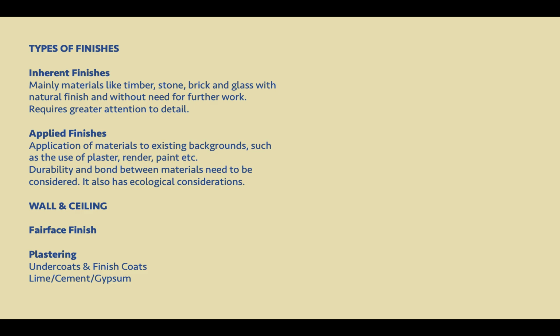Moving on from basic plaster, you will also look at plastering on timber, which will include the use of a lath. This could be a timber or a metal lath. But more importantly, a lot of current construction uses gypsum plasterboard. This is an important material to understand. It's important to understand the sizes and thicknesses.